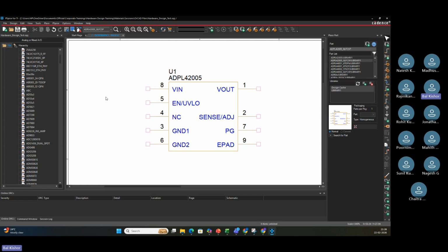So we have to keep a capacitor of, let's say, 10 microfarad. What should be the package of 10 microfarad that I can keep? I need a minimum 16 volt capacitor, because I don't want to go ahead with 10 volt or something, because the biasing makes the capacitance go very down. So I will take a 1210 package capacitor, because it has a very high voltage rating. So I'm going to take one capacitor of, let us say, 10 microfarad.